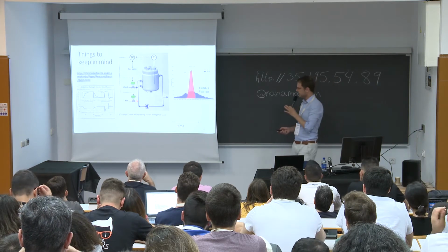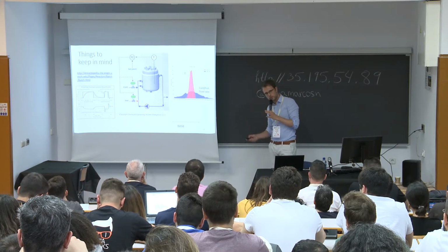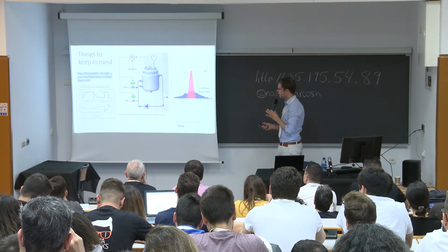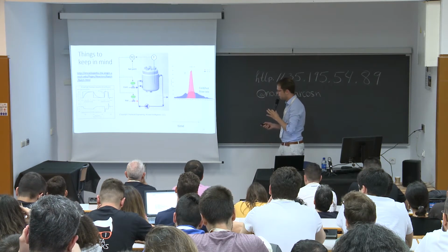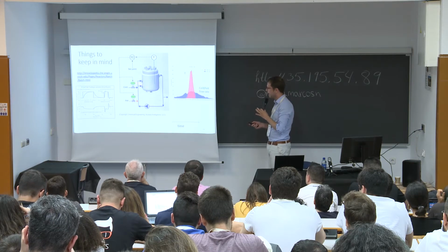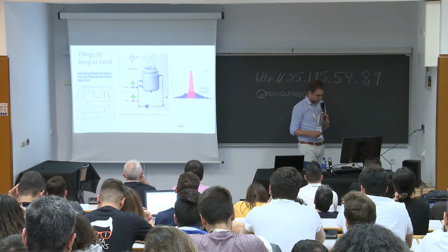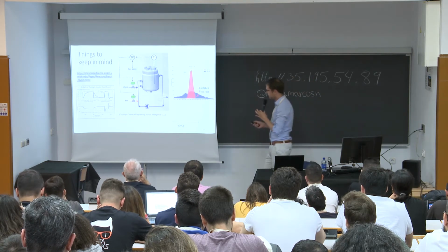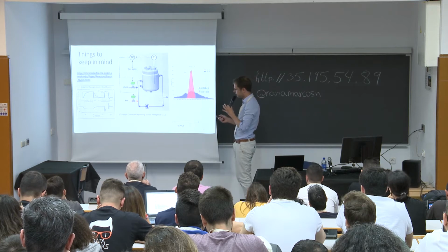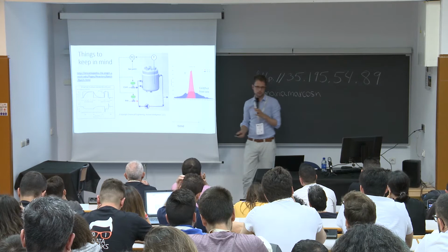Another common mistake is that I forget the process is not only at steady state, but also under control. So I have, for example, a tank, and I want to control the temperature of this tank with a refrigerant jacket. And then I start to look at the data, the distributions over time. I don't think about anything else but the variability of my data. So this is an example where I have certain variability, but if the scales are not right, I might think that this is super stable.